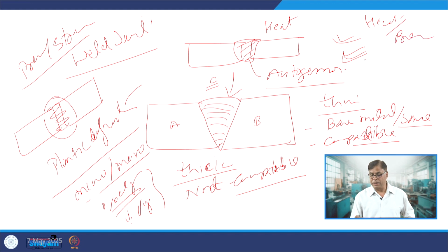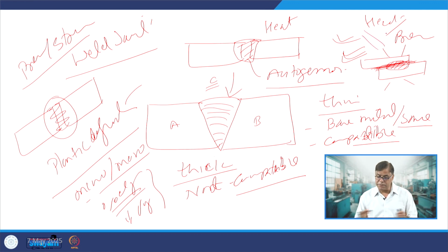Okay. So, like in spot welding, interfacial heat is generated at the interface through electrical resistance heating. So molten metal is created, and it solidifies under pressure only. Okay. So in certain processes both heat and pressure are used. So we can see, if the section is thin, or the same base metal or a compatible base metal is to be used, then autogenous welding, with no filler metal.